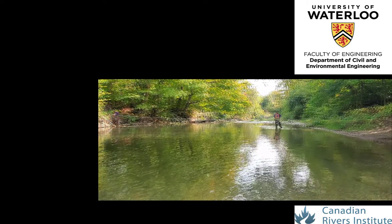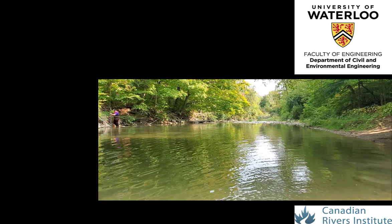The position where the water intersects the ground surface on both sides of the cross-section, referred to as water's edge left and right, needs to be recorded. Here, water's edge at the left side of the channel in the video was noted to be at 0.61 meters and the right bank as 16.33 meters. This resulted in a total flowing top width of 15.72 meters.